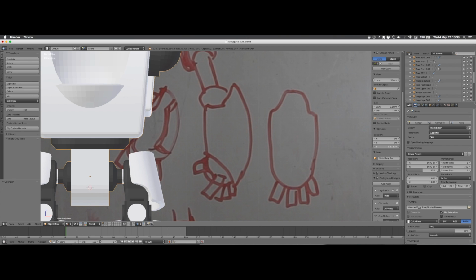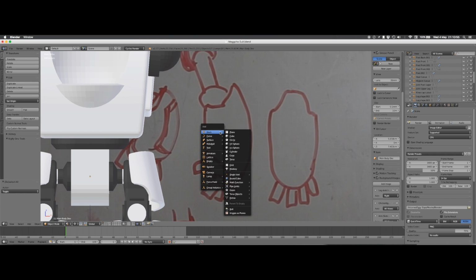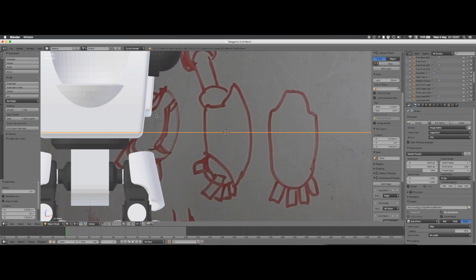There we are. I've also changed my mouse settings so that right click is no longer position 3D cursor. I use that for multiple selections of objects. Now, change its scale to 1 centimeter.